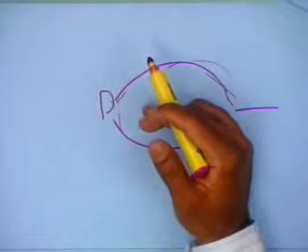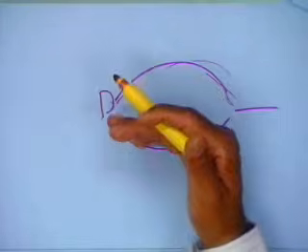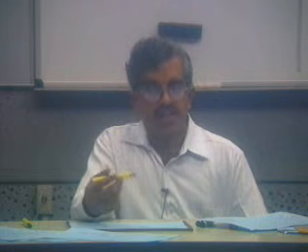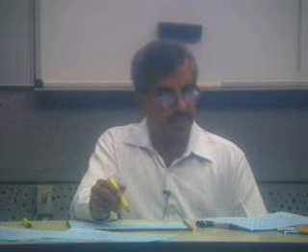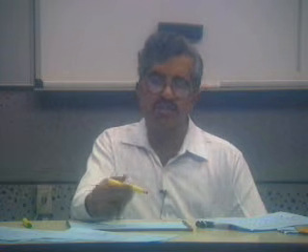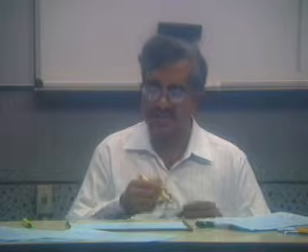If this particular point is testable, the algorithm will of course finally find a test input. But if the node is not testable, if there is no way I can transfer the fault to the output, the algorithm will fail. But you may have to do backtracking, you may have to choose the other option or the other path that you have not chosen and perform this. We will see an example of this later.